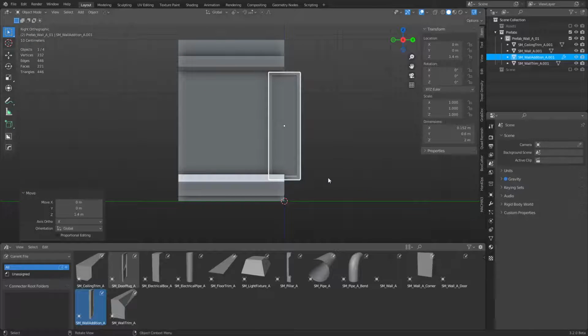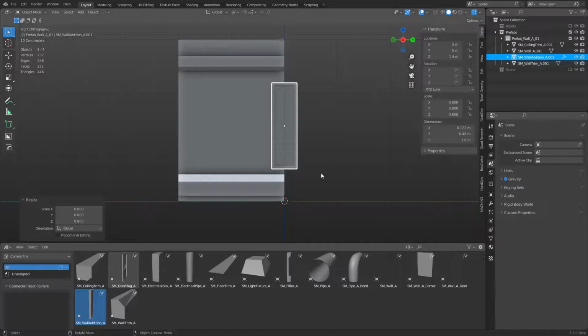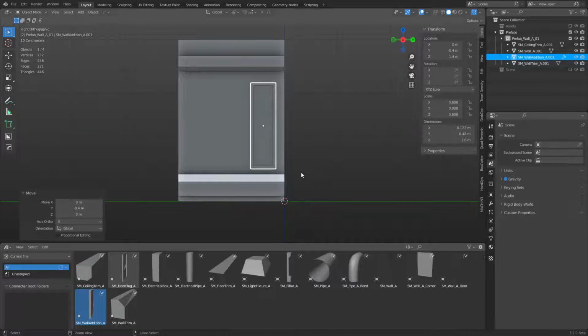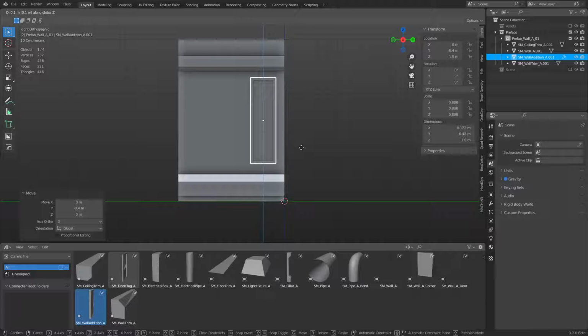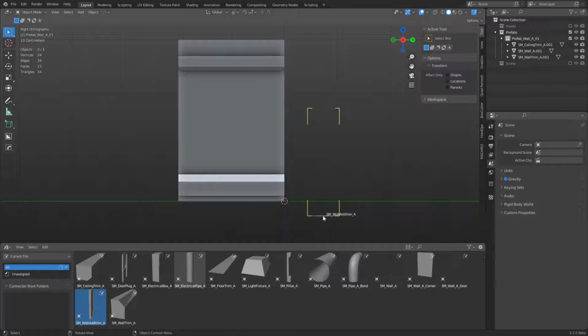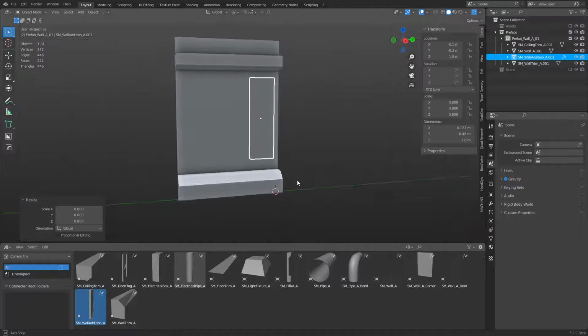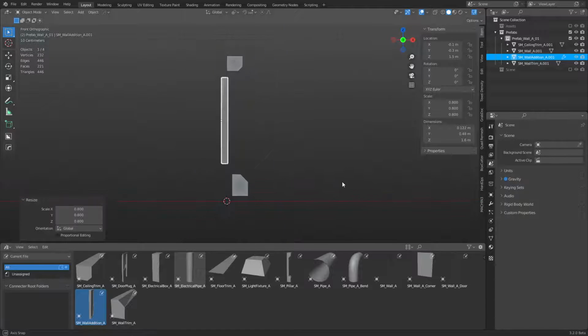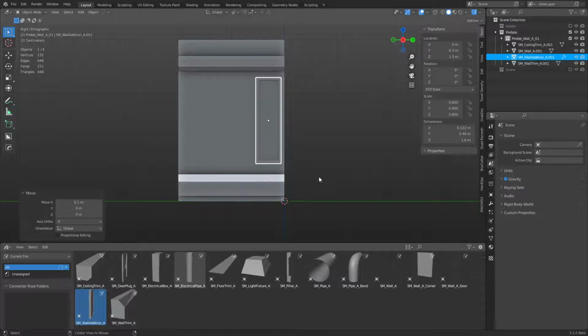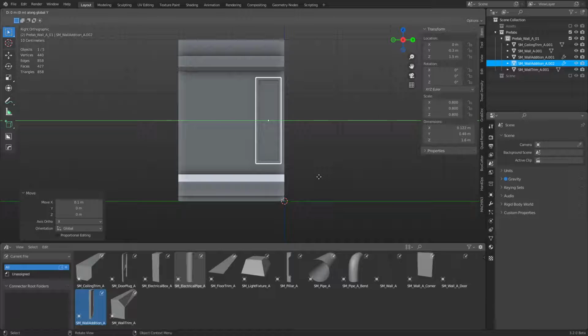It's a little bit too large, fortunately, so you can scale these, but they have to be uniformly scaled. Also, one more mention here. Scale, you hold control, it snaps, it scales it appropriately. But if you wanted to make something like this and you want to kind of array it, Alt D to do a collection or to do an instance of this.